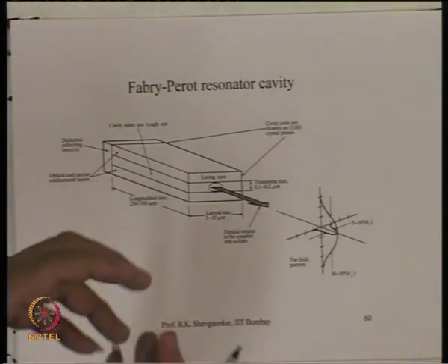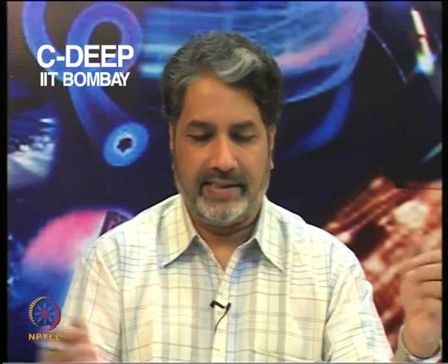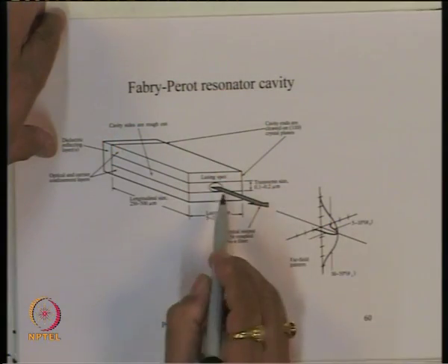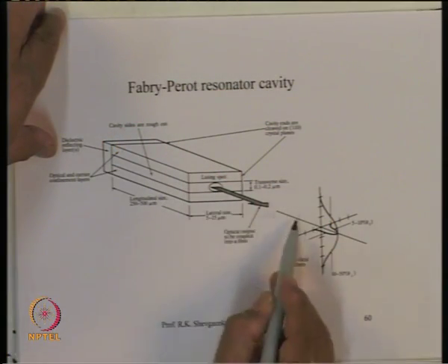Nevertheless, the angular width which you will get from this device will be much smaller compared to LED. So, you typically get a few degrees cone from this device, whereas as you remember the angular cone over which the power was coming from LED used to be essentially 180 degrees. So, the laser diode essentially gives you a beam which is reasonably narrow.